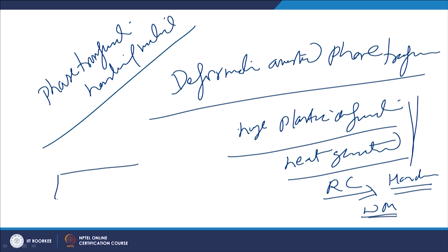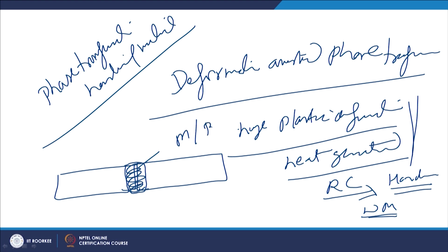For example, when steel is welded through a plastic deformation based process, huge plastic deformation of the faying surfaces leads to the formation of mostly martensite, followed by bainite and fine pearlite. While the base metal may have simply ferrite and pearlite, the controlled plastic deformation and the associated weld thermal cycle lead to the development of martensite, bainite and fine pearlite.